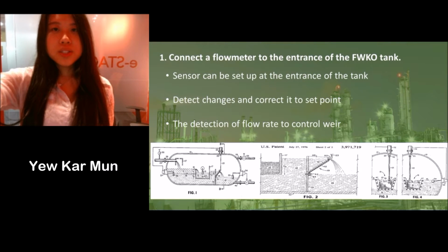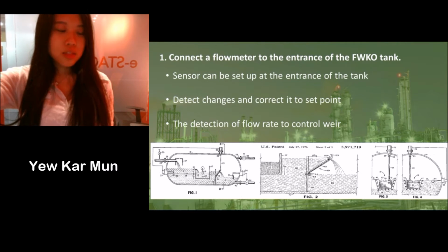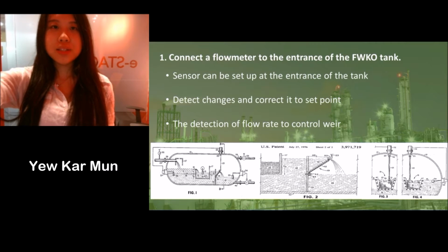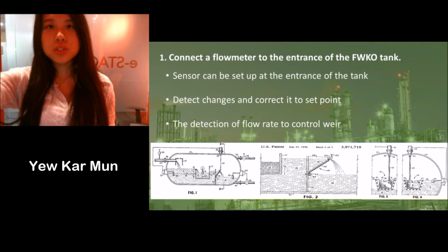First of all, the natural gas is separated from the tank by adding a gas boot prior to the tank. This will allow easier separation of the different liquids in the tank. While in the tank, controlling the weir's length adjusts the height of the water to be maintained at the desirable level. This will ensure that all three liquids discharge at the suitable exit.